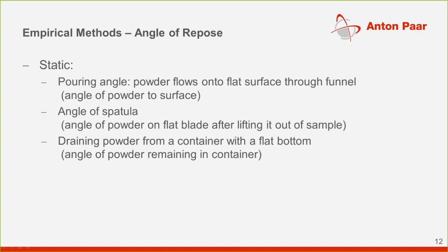Another method is the angle of spatula. So here a spatula is inserted into the powder bed and lifted out, and the angle of the powder on the spatula is measured. And the third one is the draining angle, where there's a flat container with a bottom. The powder is let to drain out of the container, and then the angle of the remaining powder is measured.